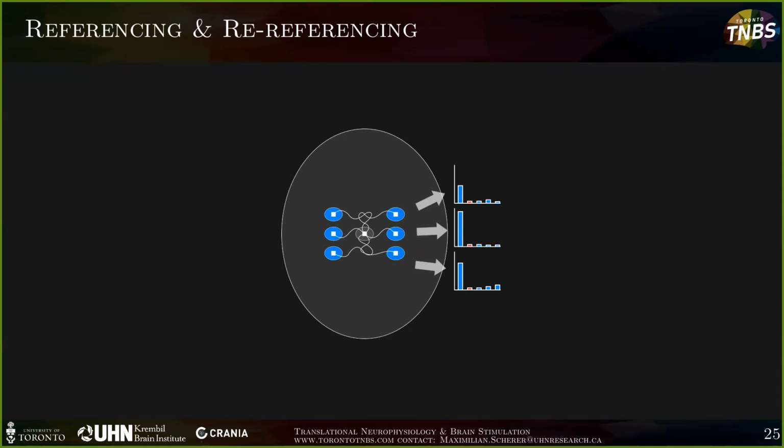So if we subtract that average, we're introducing a tiny bias by adding a little bit of every other channel to the channel we are just looking into, but we're getting rid of this huge impact of whatever was recorded at our reference.